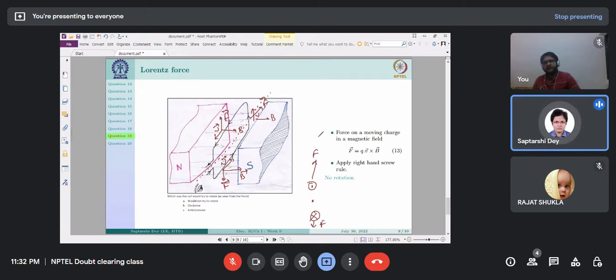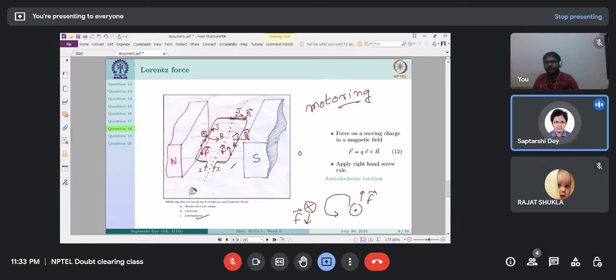So in this condition, the coil, which let us say looks something like this, is trying to bulge out. I am exaggerating obviously. This coil, due to this force, is trying to bulge out like this, but is definitely not trying to rotate. There is no force to rotate it. So what happens in motoring mode is when the coil is in this fashion, it is getting the maximum amount of torque and it is accelerating, and it is rotating in some fashion.